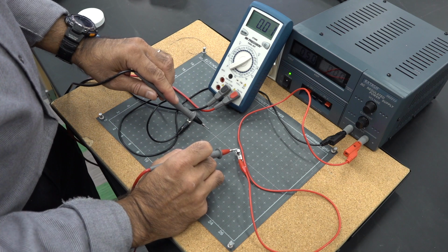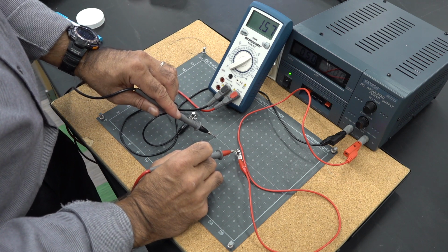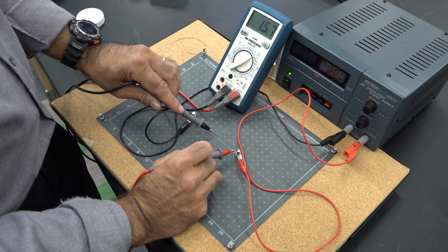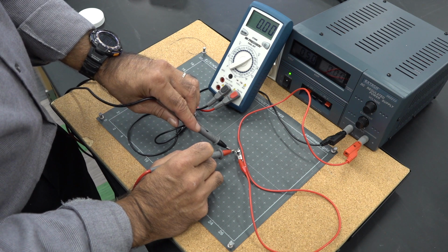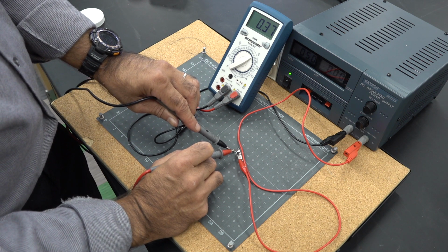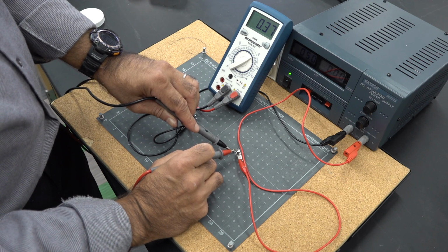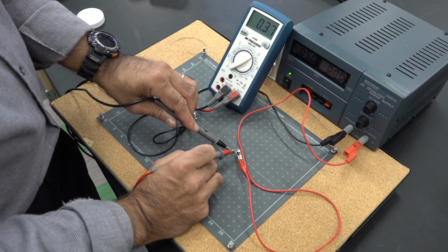So again, because of the conduction differences or how I am looking at it, this thing is not linear. It should have been linear. Or it falls away as 1 over r, actually, not linear. I shouldn't say linear. 1 over r. So right here, the difference is very low. It means if this is 5 volts, this would be 4.3 volts or so, 4.4 volts.